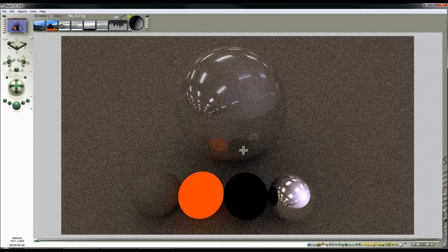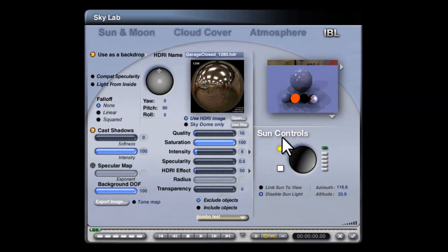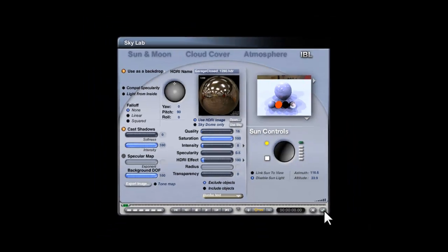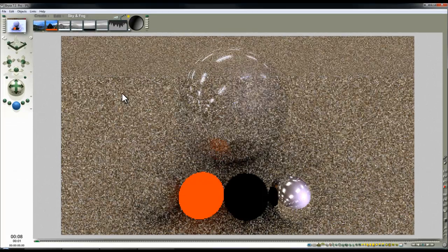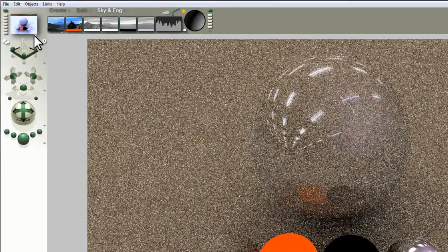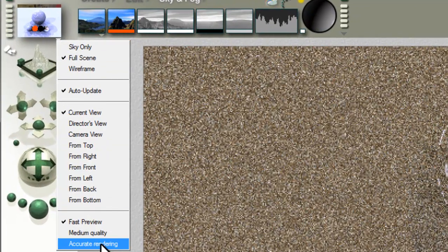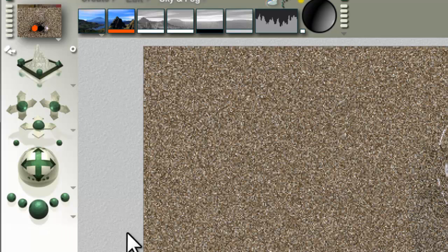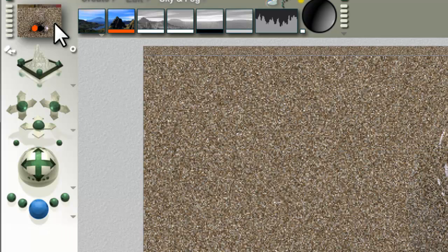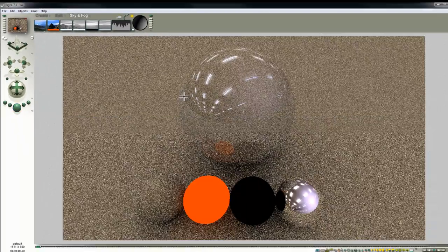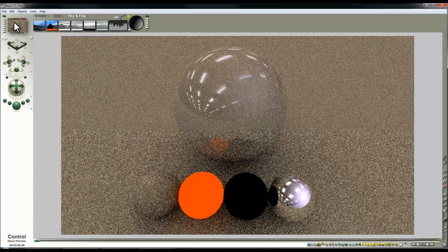The point is, when you switch over to true ambience, you've got to be aware that your image-based lighting still lights the scene through this control, and you might find you have to increase it to create better light, and a preview only shows the simulated light sources. If you want it to show a more sophisticated preview in the nano preview, accurate rendering will help you at this point, but slow down the preview here will mean that sometimes Bryce will be a bit unresponsive as it updates this little image on the left.